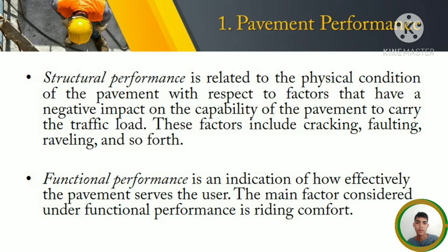So for pavement performance, the primary factors considered are the structural and the functional performance of the pavement. The structural performance is related to the physical condition of the pavement with respect to the factors that have a negative impact on the capability of the pavement to carry the traffic load. These factors include cracking, faulting, raveling, and so forth.